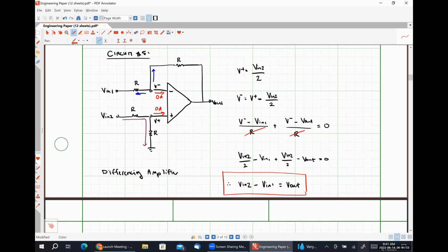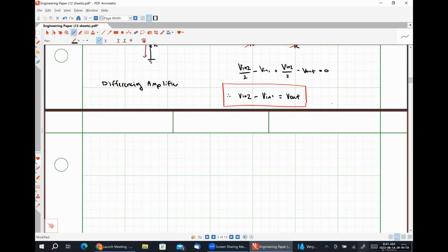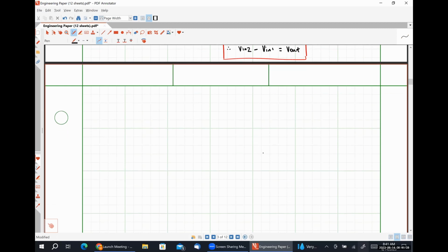Both of these circuits that we're going to talk about are really just inverting op-amps where we are replacing one of the resistors with an energy storage element. I am going to derive these relationships using capacitors, but you could just as easily implement these using an inductor.